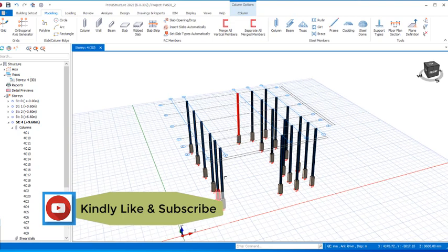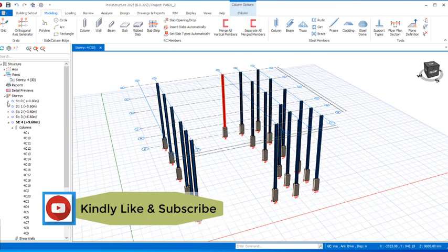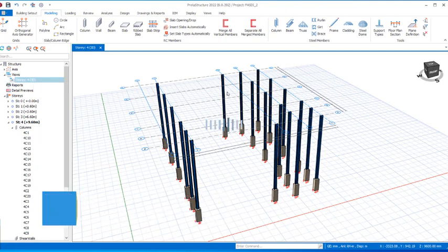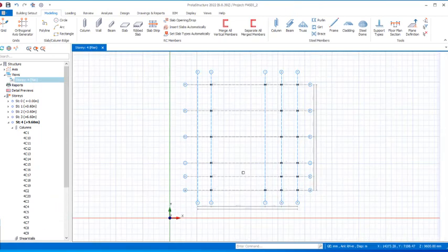All right, so now we want to be inserting the beams, so we go to the plan view of story 4. At this plan view now, we want to be placing beams in this line, in this line, and in this line. It is not a reinforced concrete beam; it is a steel structure, so steel beams.